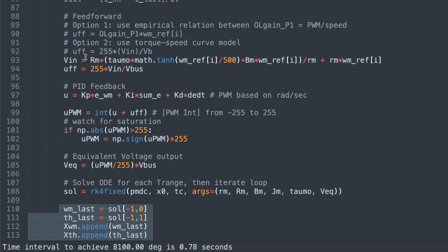At every time step, every delta t, within every delta t, it's computing all the control stuff, and then it's sending out a voltage, and that voltage is out there. It's not going to change until it comes back and recomputes new ones. So over that delta t time, the motor's doing something based on the last pulse width modulation command you sent it. It's not changing. So it's very close to what we're simulating here.